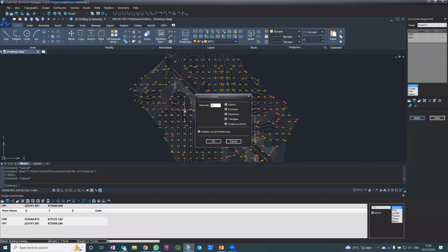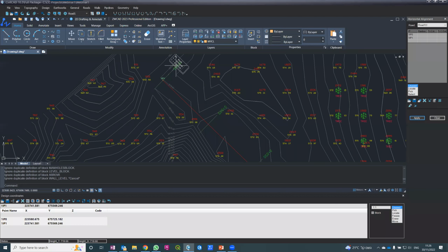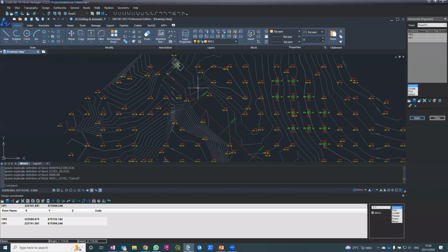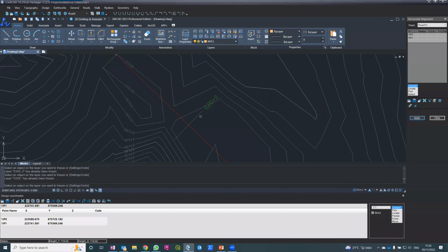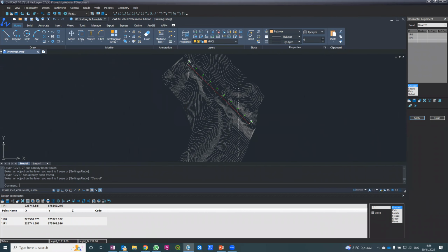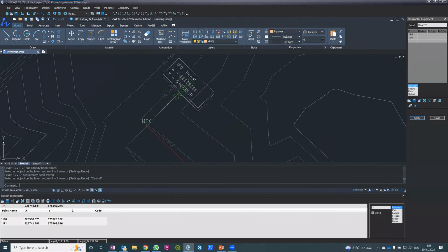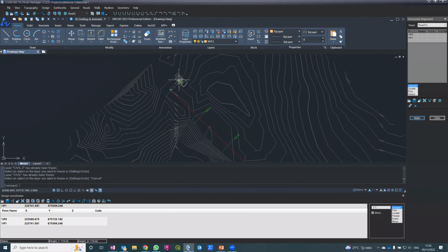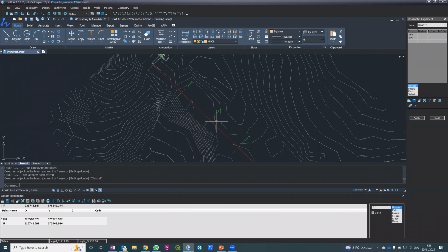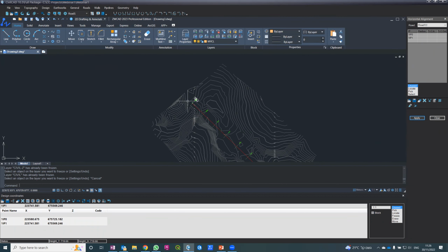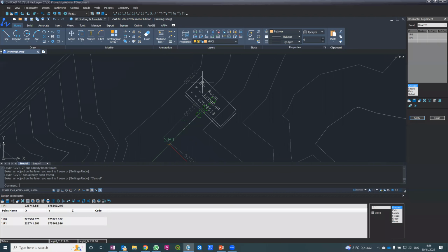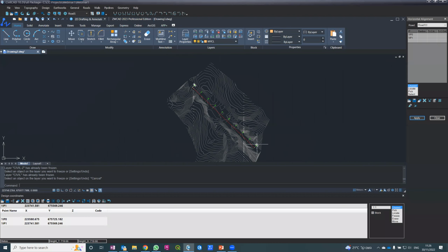then the polyline will become a beam of a road. So here it is. You can see. You know what? For us to see better, let me freeze the points. Okay, good. So now you can see this is a road that starts here at 0, and there are cross sections each, chainages if you like, each 25 meters, which is the default. And this is the first IP, and this is the last IP.